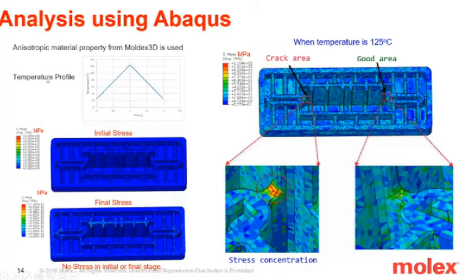What I need to do is just assign the mesh temperature from room temperature to 125 degrees C, then go back to room temperature, because this is elasticity. So the initial stress and the final stress will be zero, because it's only state dependent.